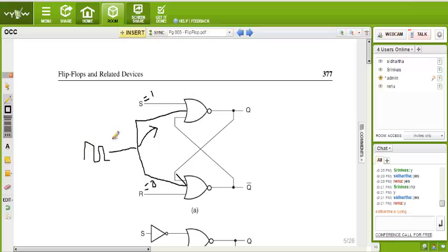One clock arrives, one time check. Another clock arrives, another check. That is why the clock is introduced to your flip flops, so that your machine is not running every time. If a flip flop is asked, you have to draw it with clock, not latch. If they mention RS latch, then you have to draw without clock. Is it clear, Siddharth?